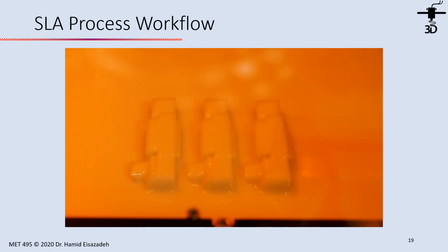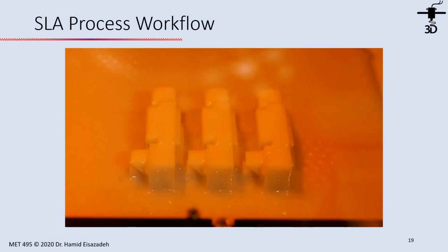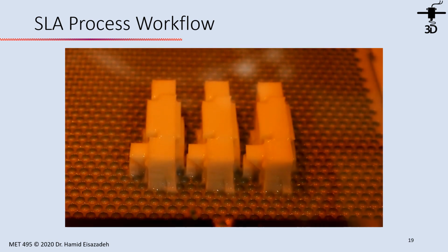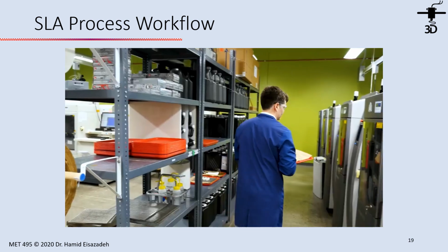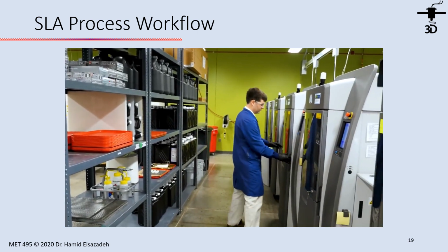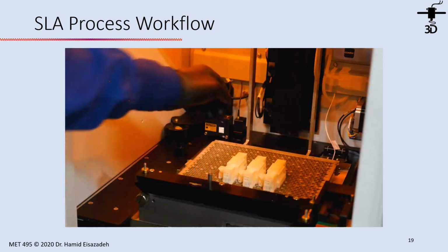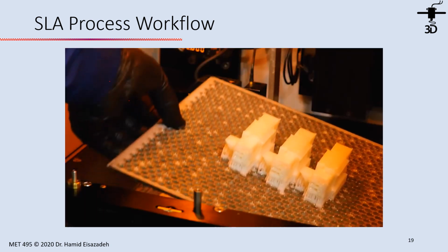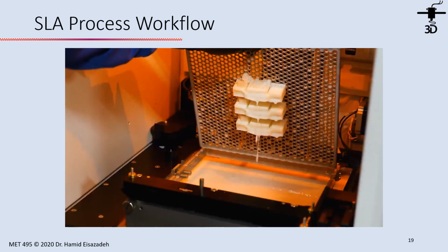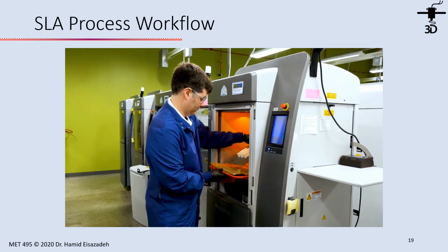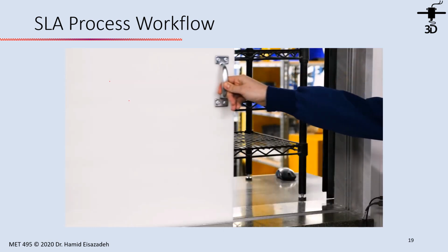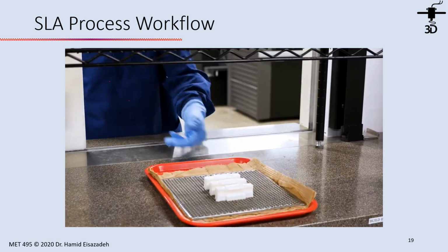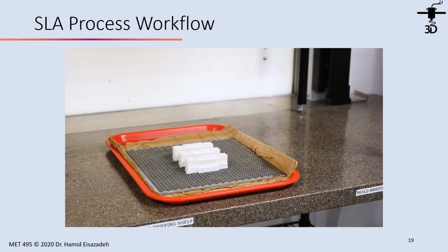After all the layers are done, when printing is complete, the machine brings the platform upward, and the operator is ready with a tray to remove the platform with the parts attached. He drains the excess resin, you can see the pass-through here from station to station, where the parts are now soaked in a liquid basin.